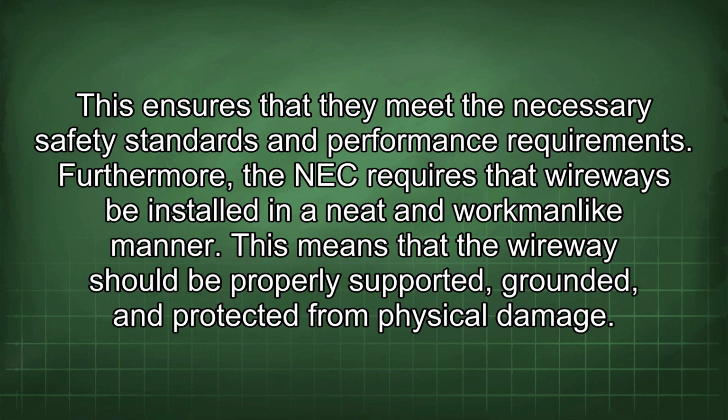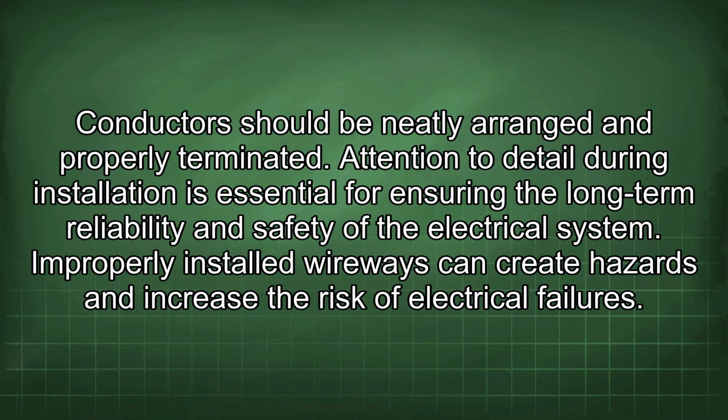Furthermore, the NEC requires that wireways be installed in a neat and workmanlike manner. This means that the wireway should be properly supported, grounded, and protected from physical damage. Conductors should be neatly arranged and properly terminated. Attention to detail during installation is essential for ensuring the long-term reliability and safety of the electrical system. Improperly installed wireways can create hazards and increase the risk of electrical failures.